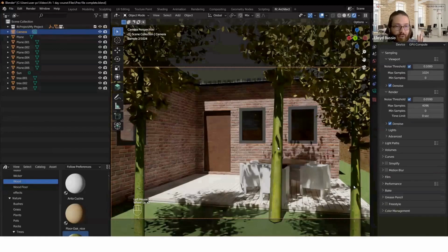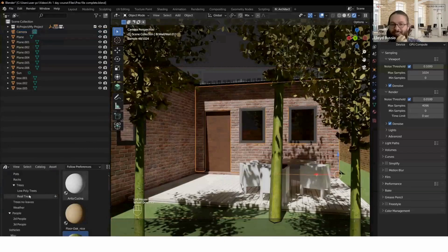If you want accurate shadows, reflections, all of that, Cycles is the thing that will check where the light is going and calculate it correctly. Eevee is kind of a game engine. It guesses what the lighting should look like. It's very close, so you can definitely use it, but Cycles is the more accurate one. So I'm shifting to Cycles here, and you can see I just turned on denoising because what it does is it creates a point cloud, essentially, of what these things need to look like. So it looks okay at a glance. I think there's a few things I want to change.